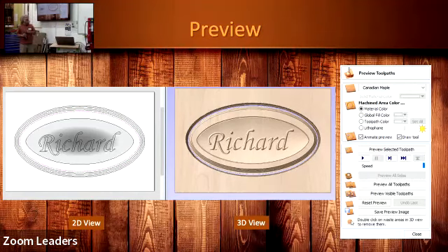Tracy mentions tabs. Tabs is an element that you can add to the design where you're going to leave a piece of material periodically around here because it knows that it's a cutout piece, and it'll leave those tabs for you to hand cut and do the final separation. Some people leave what they call an onion skin, thin, sometimes that works. But you can preview it and you will catch mistakes here before they hit the machine. And you will make mistakes that you didn't catch.